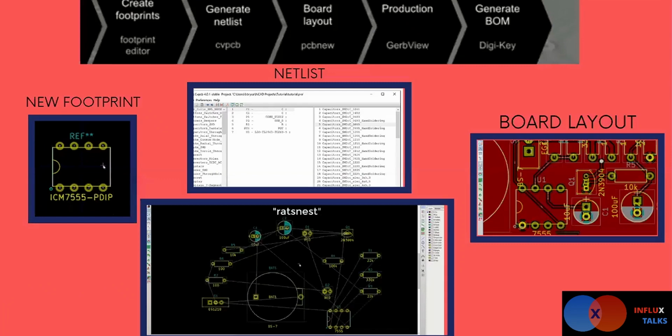The next step is creating footprints. Most of the footprints are already available in KiCAD. It's an inbuilt thing. But once you create a new symbol, you may not really find the corresponding footprint. At that time you're supposed to go and create one. So I created the footprint of the 7555 IC. It's there on the right side. I'm sorry, it's on the left side.